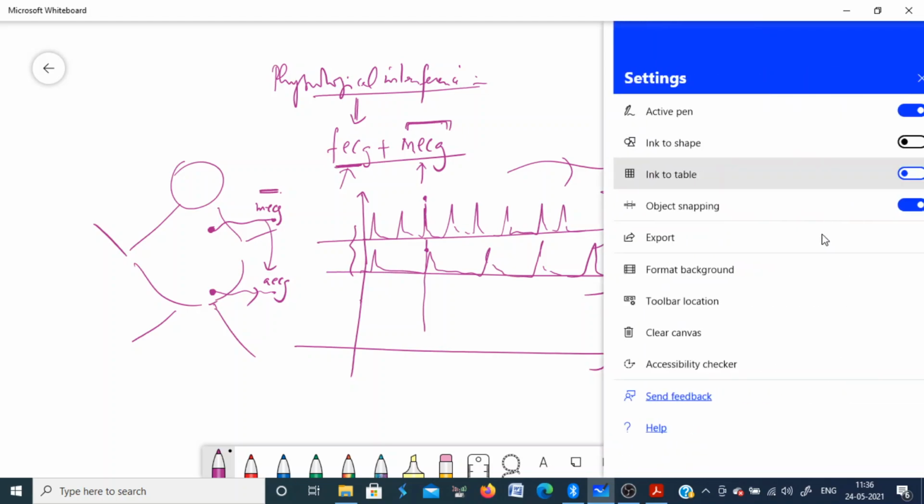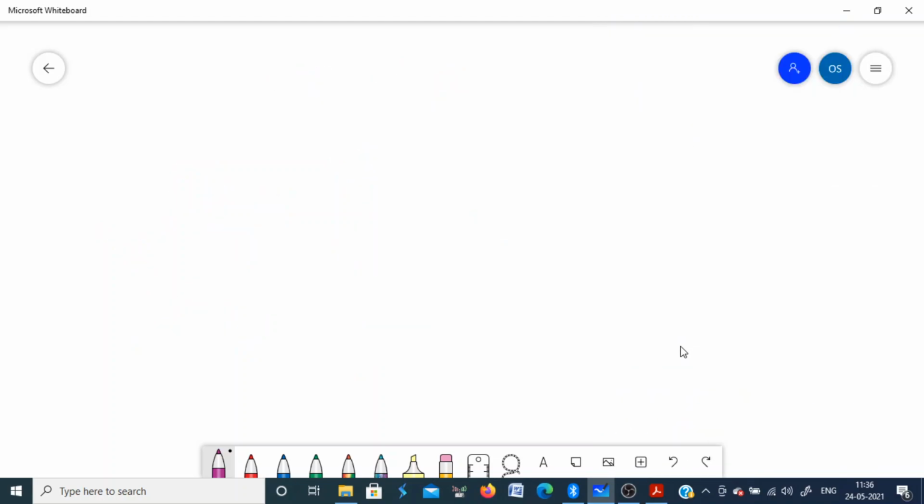So random noise. Most of the noises that you get in these biomedical signals are random in nature. Like EEG is a random signal, PCG is a random signal, EMG you can say is a random signal. If you talk about the ECG signal, it is not periodic, but you can say it is cyclo-periodic, quasi-periodic, because every heartbeat is not the same. There is somehow a difference between two heartbeats, so it is not exactly periodic, but it is quasi-periodic.